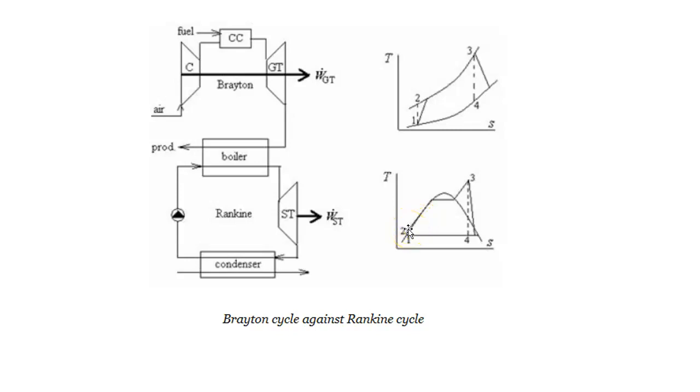So then evaporation happens from this point, and then our superheater increases our efficiency at this point, and work output at the turbine occurs from 3 to 4. When we reheat it, the actual line comes out a little bit, and we get a little more efficiency, more surface area in our T-S diagram, and then it'll exhaust in the condenser. That'll be our heat sink.